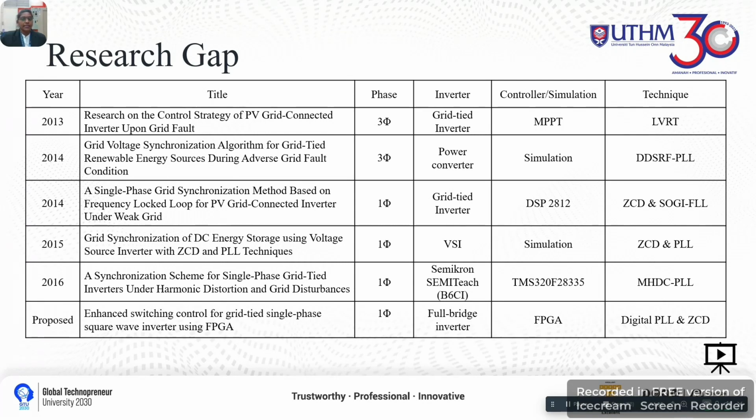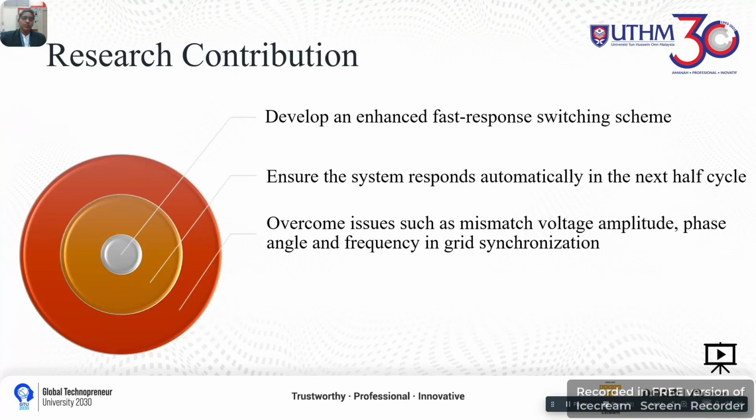The significant difference between the earlier studies and this research is the digital implementation based on the FPGA to generate the square wave switching signals with third harmonic elimination for the full bridge inverter for a faster response. Thus, the contribution of this research is developing an enhanced fast response switching scheme to ensure the system responds ultimately in the next half cycle.